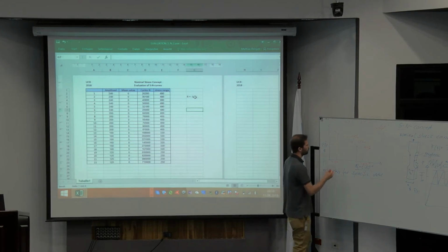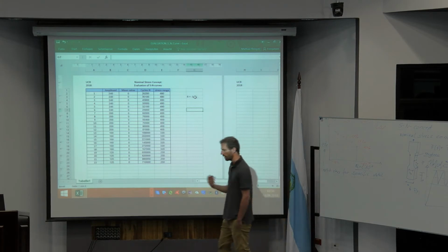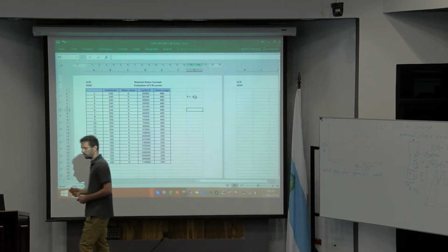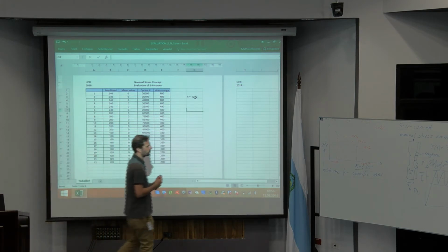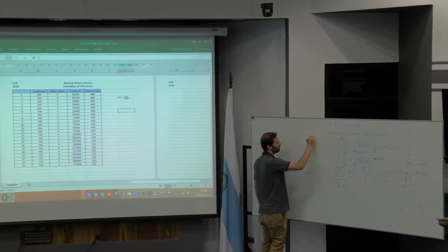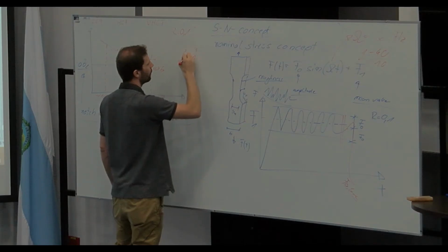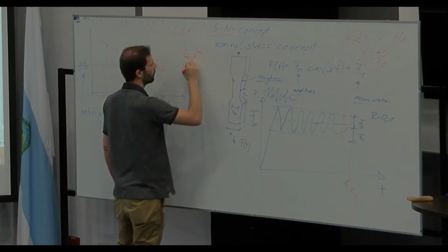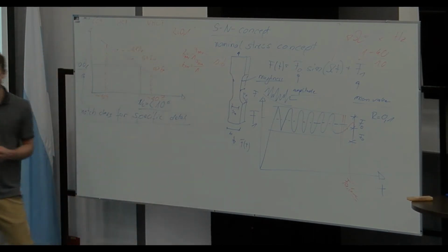As you can see here, we are still in the elastic range, we want to have just elastic behavior, and due to the elastic behavior, we can calculate our stress range, which is always F/A, and at the end, we can calculate our delta sigma.